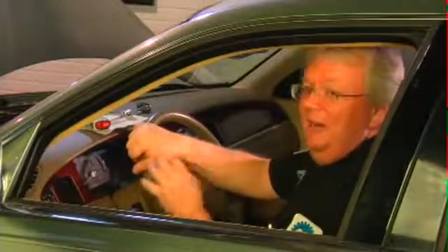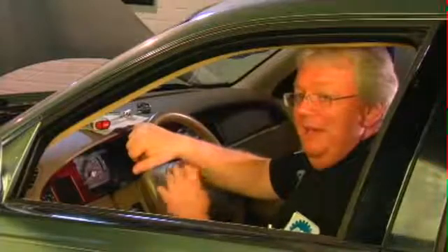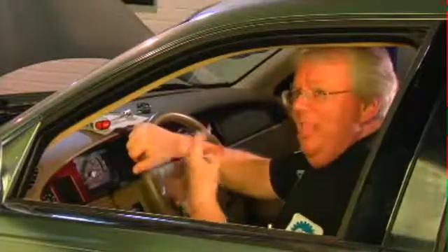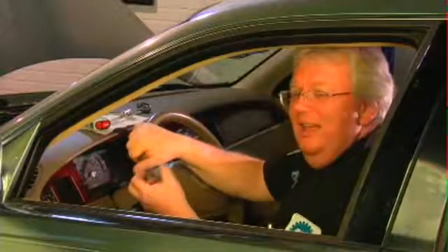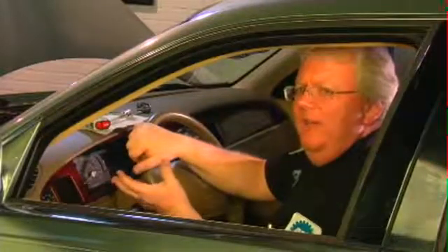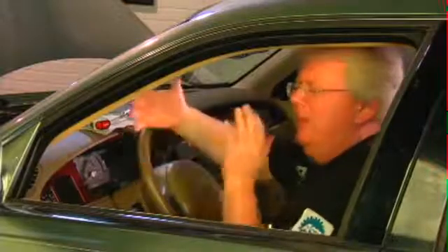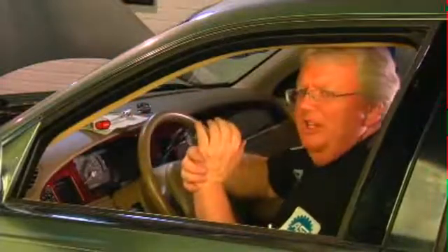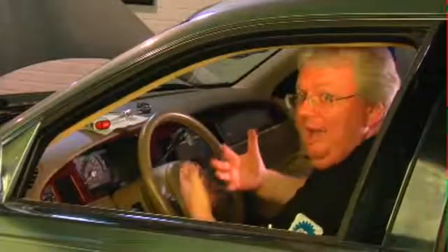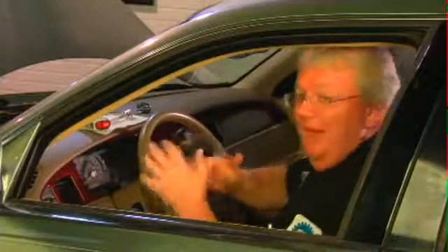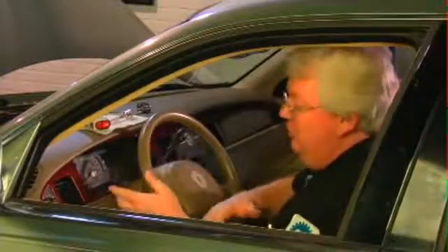So take the negative battery cable off and wait a minute, which we've done. Now, what that minute wait is, airbag modules contain capacitors that store power in the event of a battery failure. So if the battery is smashed in the frontal collision and there's no power then to deploy the airbag, it's like model rocketry. A little bit of power and ground, even from a 9-volt transistor radio battery, as I already mentioned,